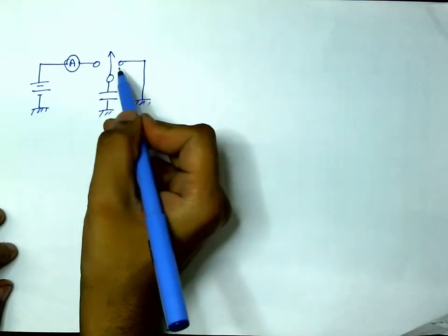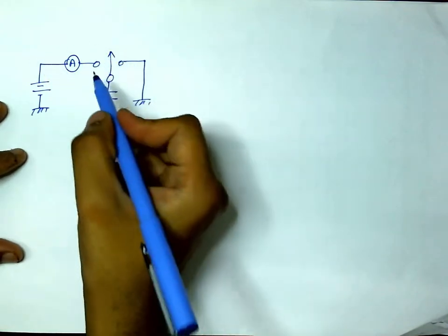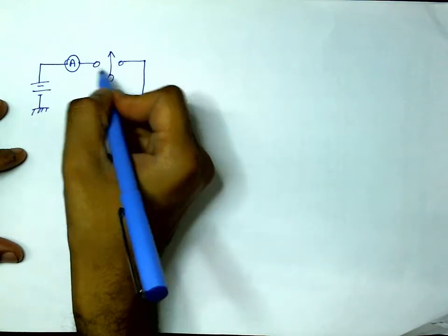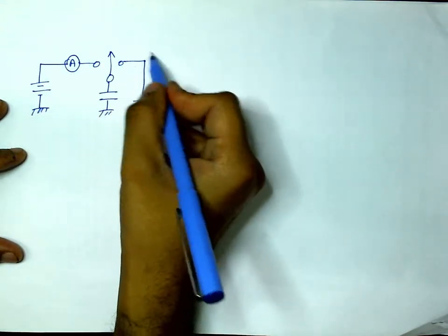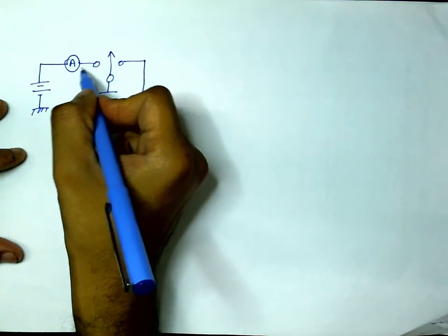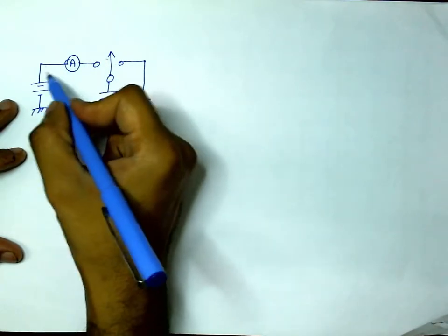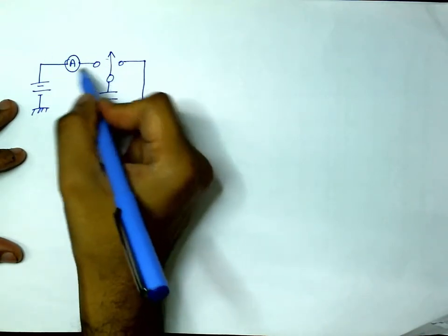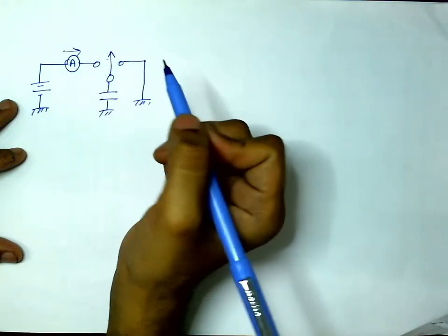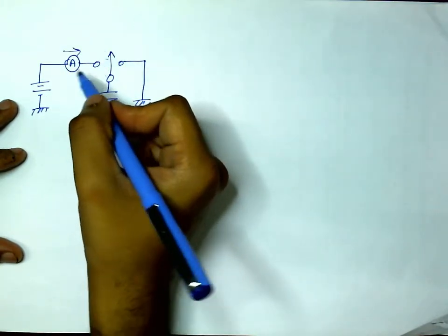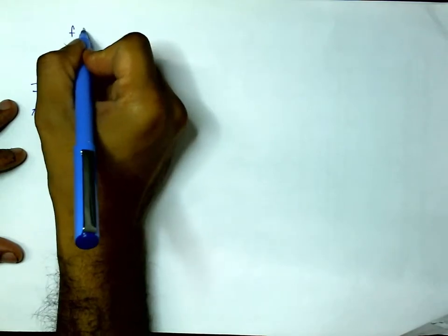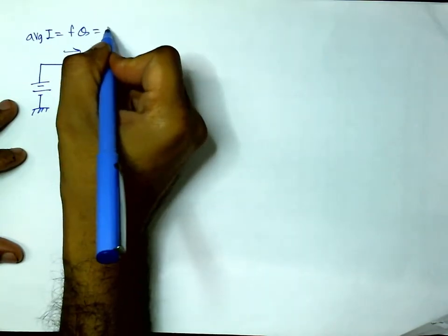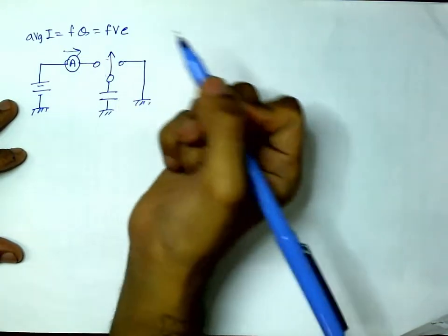Okay, so the capacitor will be charged through the ammeter, and the amount of charge it will collect will again be Q equal to CV, but that comes through this, and it will discharge through this. And then if this switching frequency is F, then the charge that the capacitor collects per second is Q multiplied by F, that goes through the ammeter, and that is the average current, which will again be F times Q, equal to F times V times C.